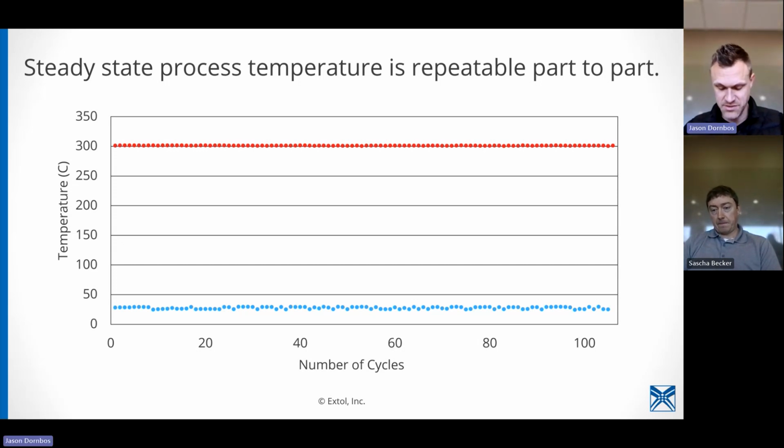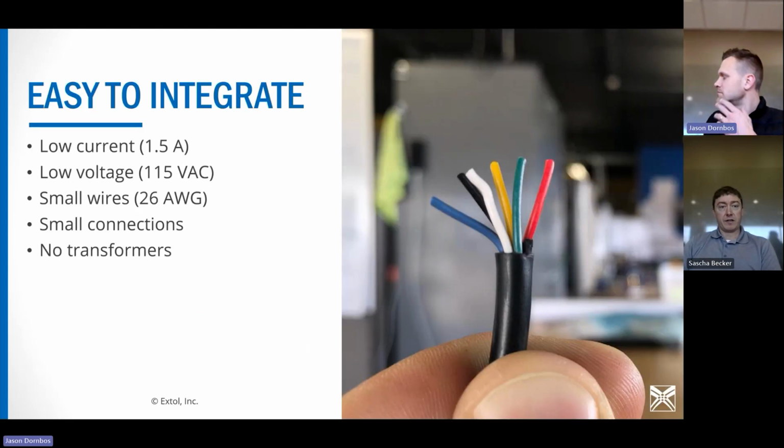And do you recommend any coating on nanoSTAKE? We do some hardened coatings. We do like to try a couple different things, kind of tailor it to your needs if we can. If your material has anything abrasive inside of it, like a talc filler or a glass filler, typically we would harden the tips of the nanoSTAKE modules to reduce the wearing that happens on those.